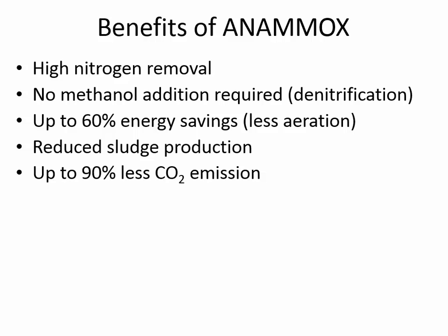ANAMMOX has a really low yield. Remember, yield, Y, is a measure of the VSS that grows for some substrate consumed. It could be the COD that's consumed, or in our case, the VSS that grows for the NH4+ that's consumed. A low yield is a good thing, because we want these microorganisms to eat a lot of food and not gain very much weight, because eventually we're going to have to dispose of the biomass.